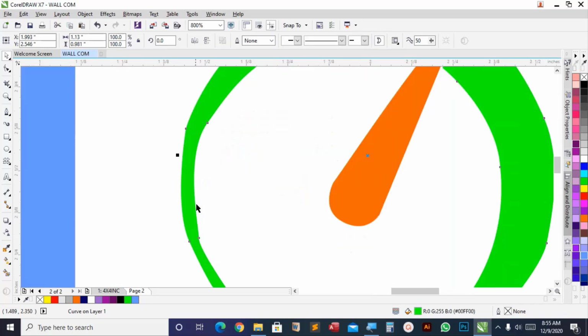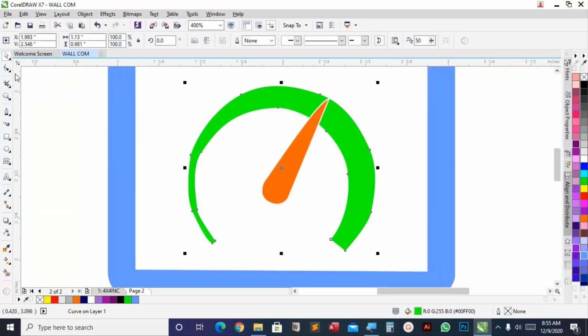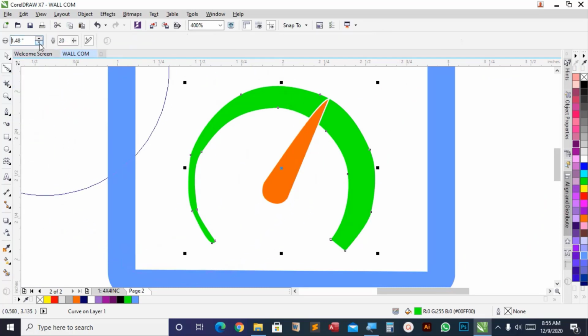And when you want to see that everything of yours is very smooth, you just have to click on it, come to the shape again, right L, just click, and then go to the smooth. Then you can decrease the size here. So maybe let me write 0.5 there, enter, and it to be a bit small. Then I can just drag around it, and then you see that it is now smooth, very smooth.